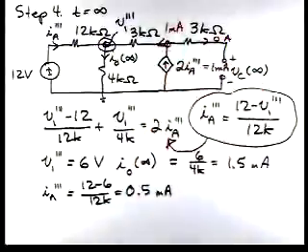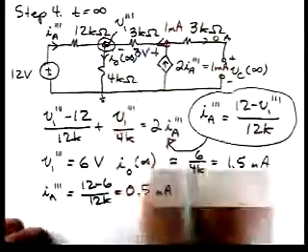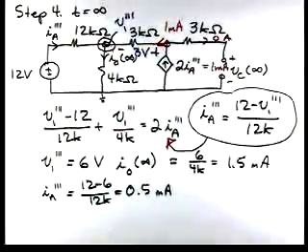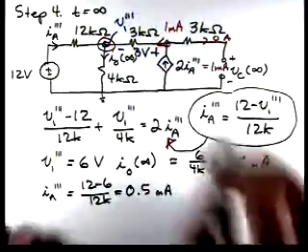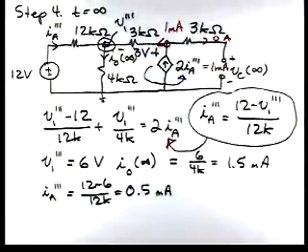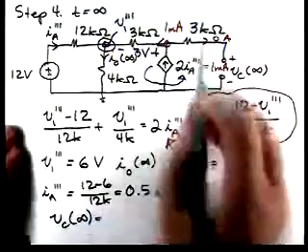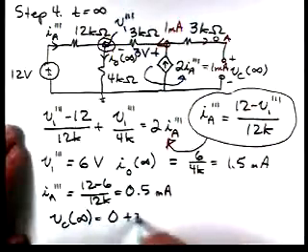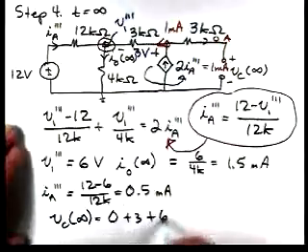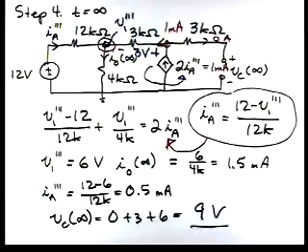And that tells us there's 3 volts across that 3K resistor. Now we can get VC of infinity by going around this loop. So VC of infinity, we have 0 there, 3 volts here and then 6 volts, so VC of infinity is 9. We're going to use that in just a second. I thought I'd go ahead and calculate it while we were at this circuit.